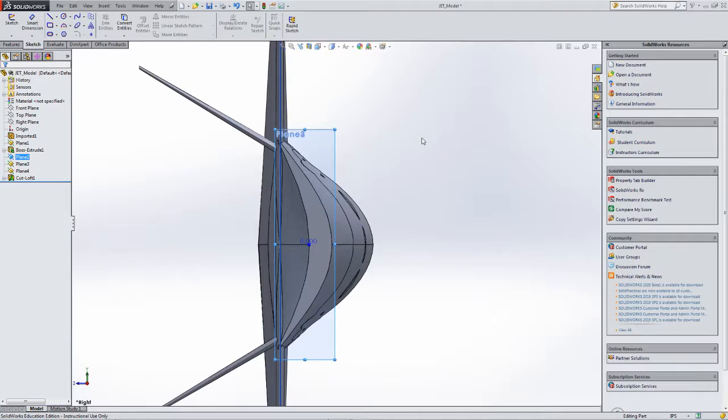And I'm doing that deliberately because I want to show you something about being at full scale. So we're going to make this 0.421 inch at full scale. We imagine the wind tunnel model being 1/48 scale, so we're just going to make the radius 0.421 times 48.